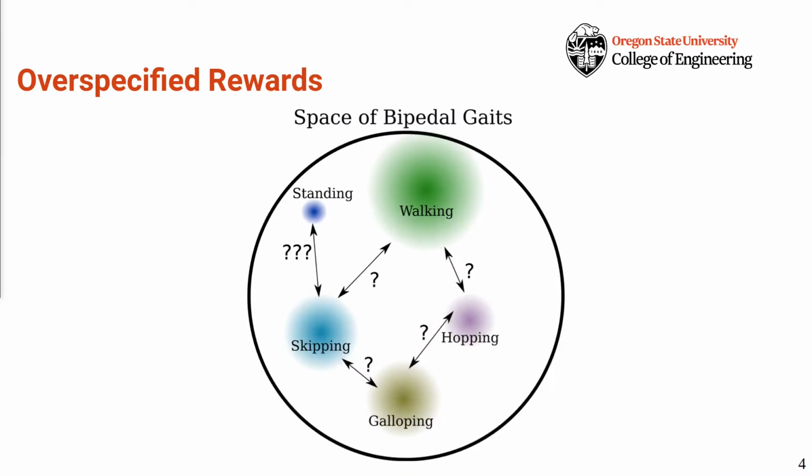Reference trajectories can also limit the way your policies explore the environment during training. If reacting to a disturbance or responding to the environment in some way results in a trajectory of joint positions too far from the reference, the reward will be needlessly low. This limits the type of experience the policy can collect and can stop your policy from learning robust or error-correcting behaviors which happen to stray too far from the reference motion.